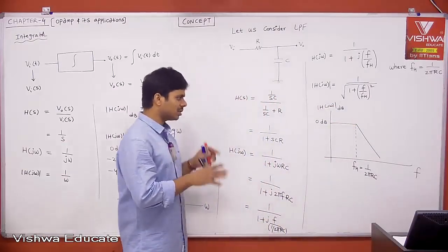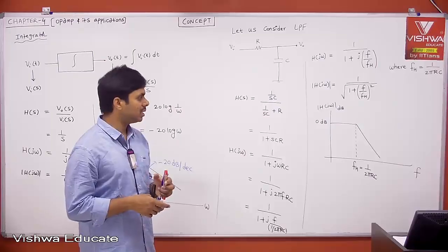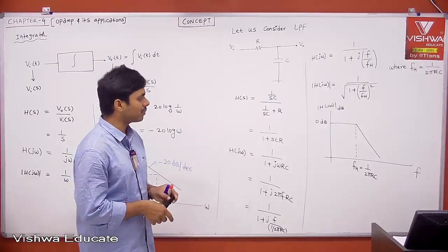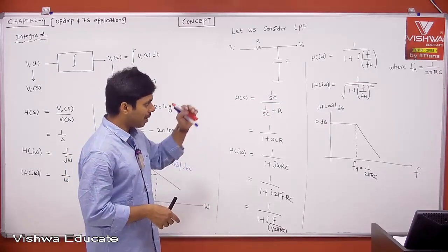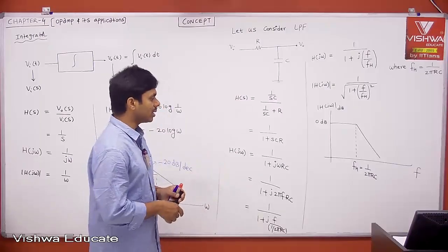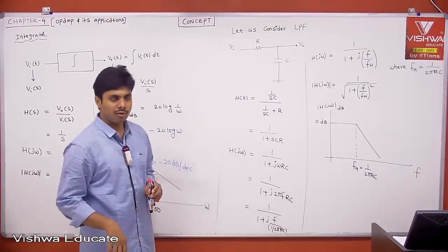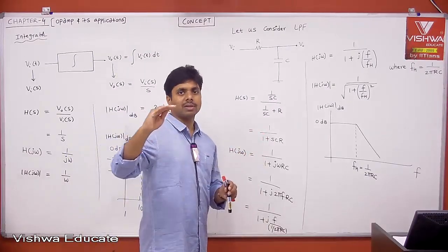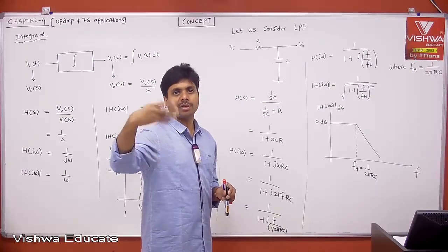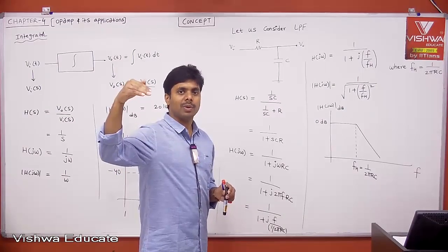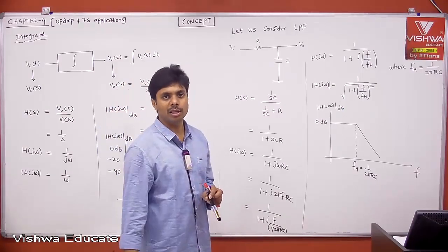But strictly speaking, this is for easiness, because if you want to draw a magnitude response from the transfer function, then find the poles and zeros. Wherever you have a pole, till then the frequency response is flat. Then whenever you see a pole, the frequency response will be decreasing with a slope of 20 dB per decade.